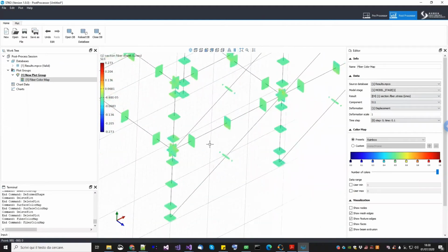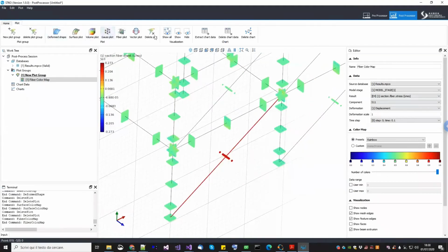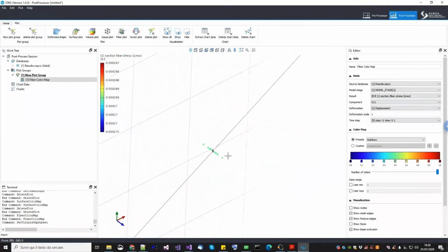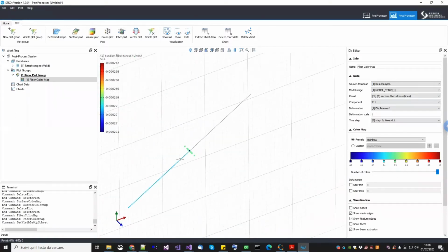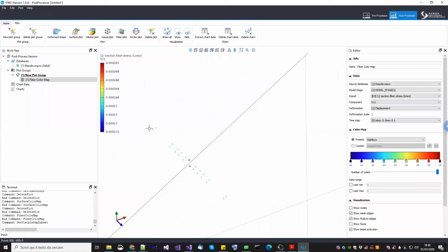Now I want to isolate this one to explain to you how it works. Okay. So this one is the model of the infill. As I said, it is made of 2 elements. Each one of them is a beam with hinges, where here you have an elastic pin section. So an elastic section with an almost 0 out of plane bending stiffness. So it simulates a pin. Same thing here. Here you have an elastic section, a regular elastic section to simulate the elastic stiffness of the wall. And in this point, you have a fiber cross-section.